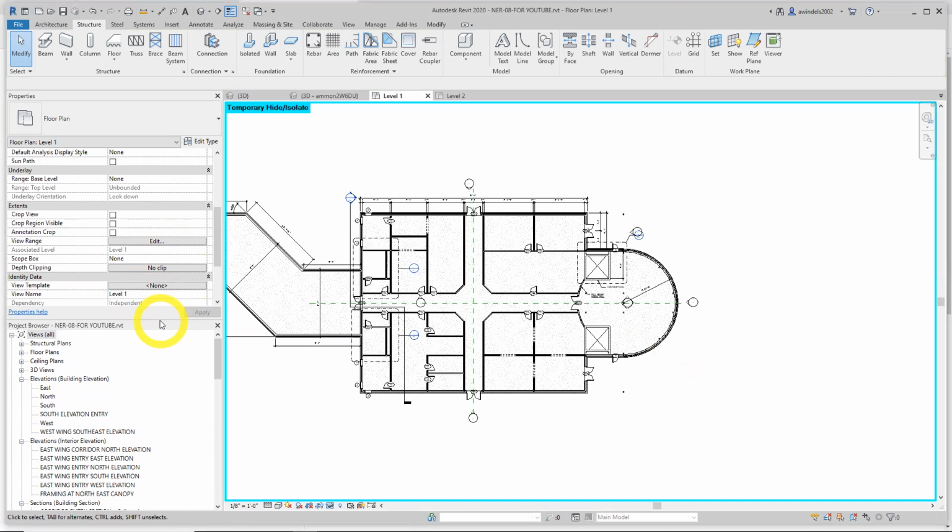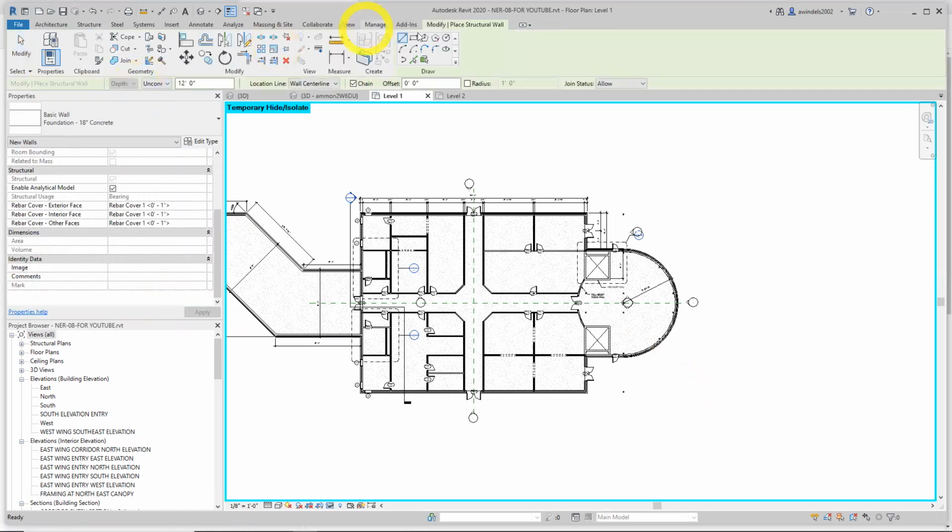Page 408. Let's start by building our wall now. Lines. So foundation walls are a little different. Columns are placed top down. So depth rather than height appears. And that's our only option in this case. Let's set our depth to, very important here, top of footing level. Justification, wall center line is all good. Offset can be left alone.